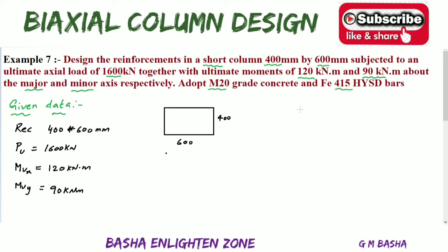So observe the difference between the previous problem we solved in example 6 in our channel. In example 6, they give a load, some Pu, and moment, some Mu, only along the major axis. But here, the difference is that the moment is considered from both the x axis and y axis, about the major axis and minor axis respectively, so two moments are acting on a particular column. This type of column is called a biaxial column.